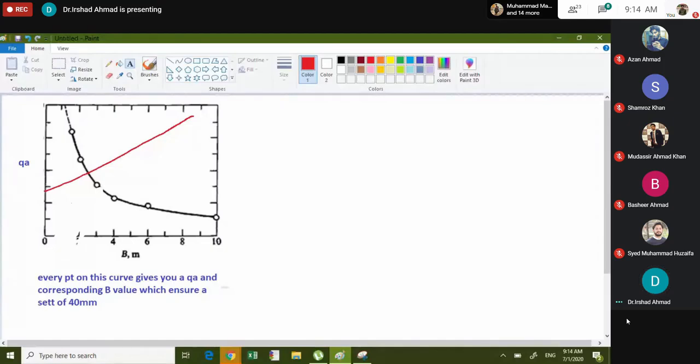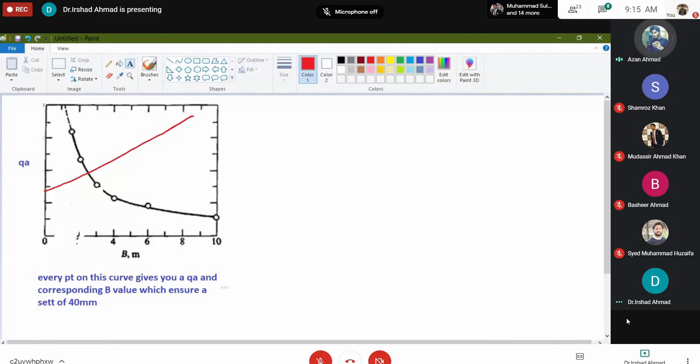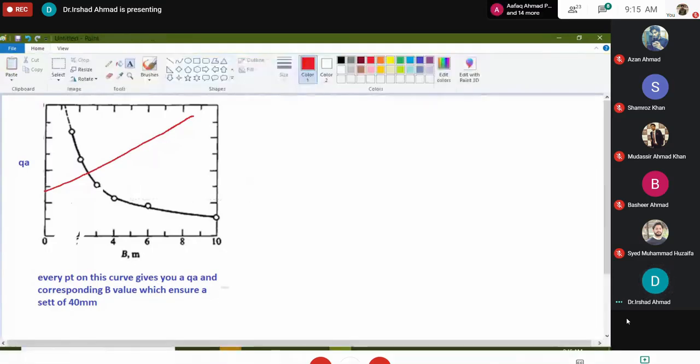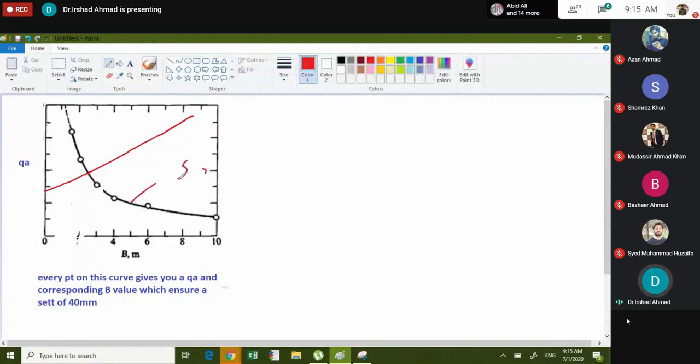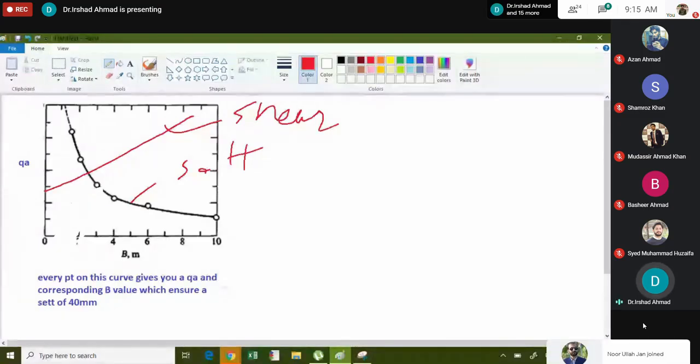क्यों अलाउबल? हमारे पास दो क्राइटेरिया हैं जो टेक्निकल डिजाइन में, किसी को पता है वो दो क्राइटेरिया क्या हैं? स्ट्रेंथ और सेटलमेंट। शेयर फेलियर क्राइटेरिया है और सेटलमेंट क्राइटेरिया है। तो ये सेटलमेंट क्राइटेरिया हो गया और ये हो गया शेयर। तो क्यों अलाउबल क्या होता है? दैट इज मिनिमम प्रेशर दैट विल नॉट कॉज शेयर, मैक्सिमम प्रेशर दैट इज मिनिमम ऑफ द सेटलमेंट क्राइटेरिया एंड शेयर क्राइटेरिया। ठीक है ना?